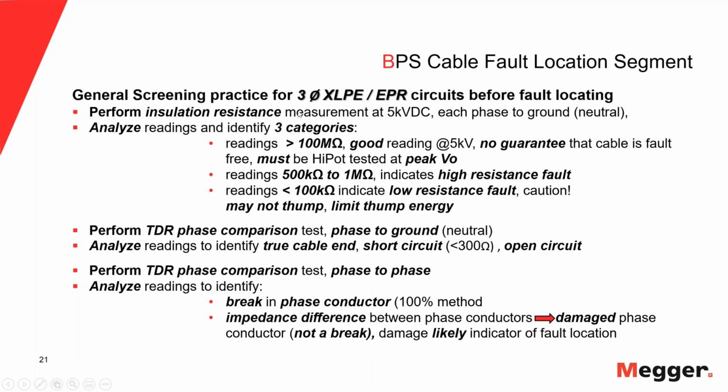When we do fault locating, it's always good not just to go out and hook the thumper up and pray for the best. It's good to do some screening. So what can we do in terms of screening to learn more about the type of fault we have? Because in the end, the type of fault determines what fault locating method will work best to find that fault in the quickest possible way.